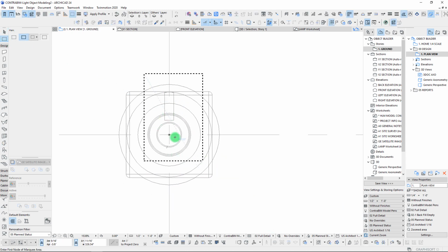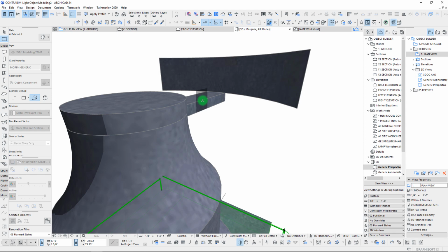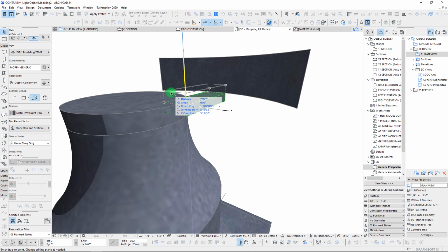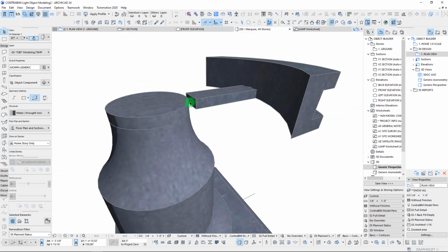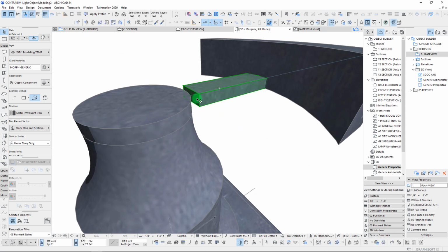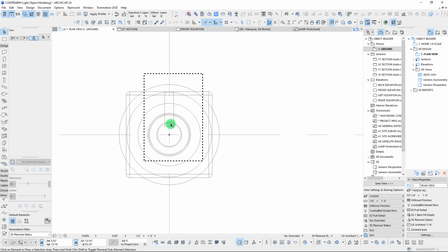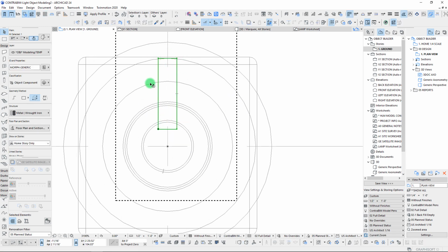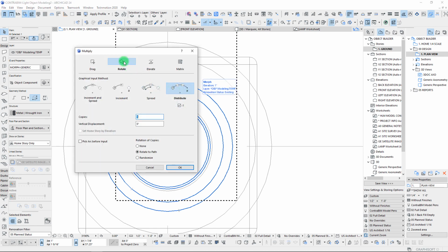So what we can do is let's just cut a marquee right through here, and then let's get these two connected. So we'll take this, pull it up 1/4 inch, and then we can simply offset this by clicking on the face. We'll just offset it in, and then we'll end up connecting all these. So, okay, there we go. We're going to take this segment here, and we're going to do a Control U. So this will allow us to rotate.